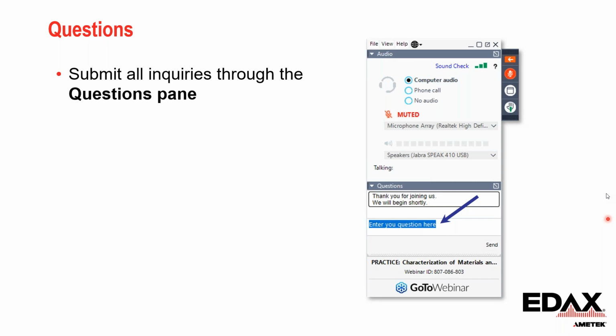For example, for the transition metals, you have peak overlaps for the L lines, so you can go to higher kV to excite their K lines, and you have very little peak overlap in that higher energy region. But the problem, sometimes